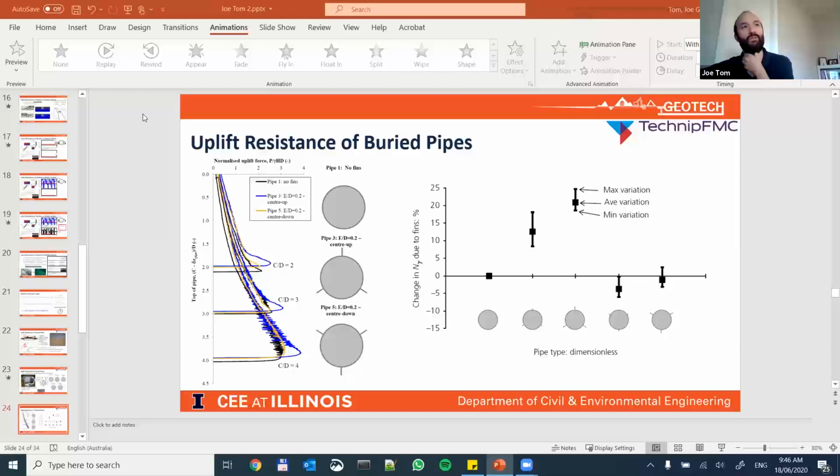And just in general, we see a lot of higher friction angles in the carbonate sediments as compared to, I suppose, more traditional silica sands. And so that would need to be incorporated in terms of the values of the friction angle, critical state and peak friction angles, that you use. Those are the sort of two things that come off the top of my head. Sure.